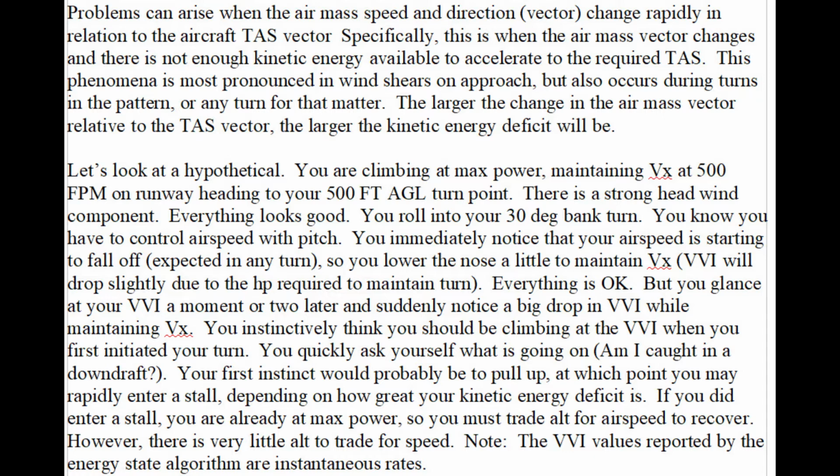Am I caught in a downdraft? Your first instinct would probably be to pull up, at which point you may rapidly enter a stall depending on how great your kinetic energy deficit is. If you did enter a stall, you are already at max power, so you must trade altitude for airspeed to recover. However, there is very little altitude to trade for airspeed in the pattern. Note the VVI values reported by the energy state algorithm are instantaneous rates.